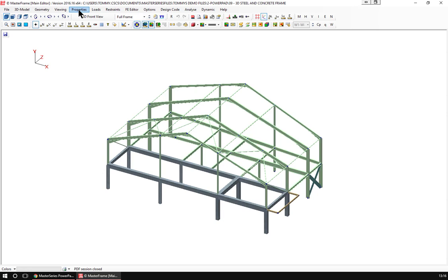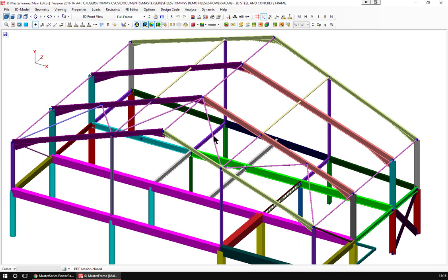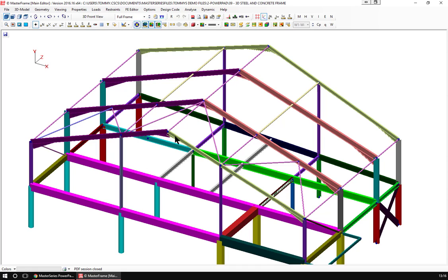and we will see not just the steel properties, we can actually turn on different colors for different section sizes. So we can see immediately that that's very thin and that's not, so that should be the same as that one or that one. So what I can do is go to properties, steel sections, section sizes, and I can correct that.